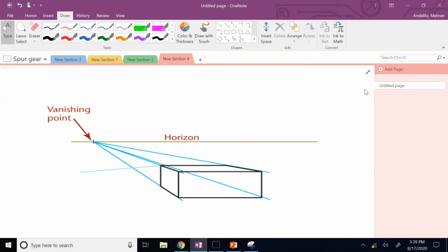Right, so this is what I have. And instead of that, I now go ahead and put my vanishing point here. VP, vanishing point. How does it look if I do that? So the front face of the object, I draw it full scale. Okay, so this face here, this one and this one, the scaling on the height and the width is what? 1:1.